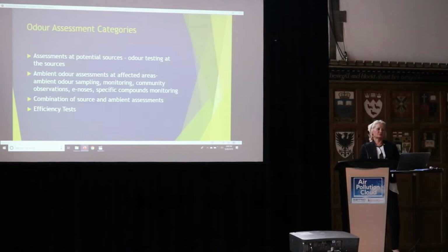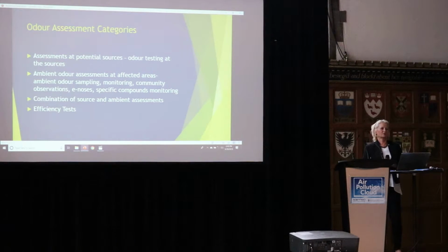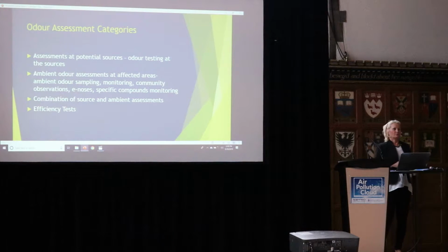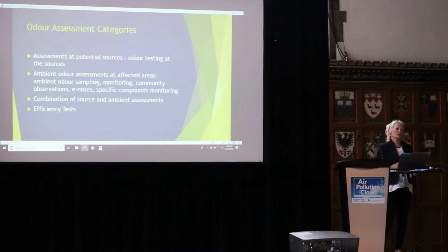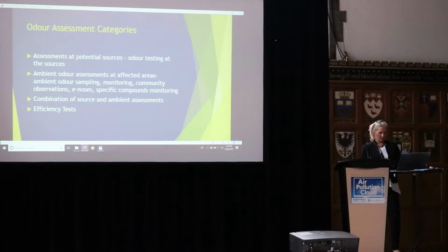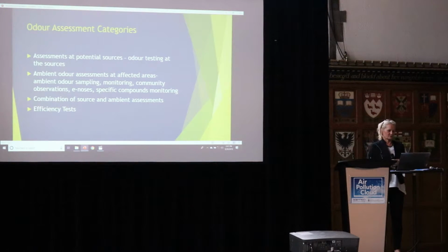There are different categories of odor assessments. Odor assessments basically are source testing at the source, and then the emissions are used for dispersion modeling to predict the outside concentrations. Also, especially in Ontario, the ministry allows collecting samples at the sensitive receptor and doing the odor evaluation of the samples collected at the sensitive receptors. There might be a combination of source testing and ambient assessment just to do the full